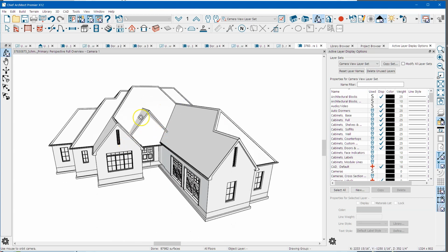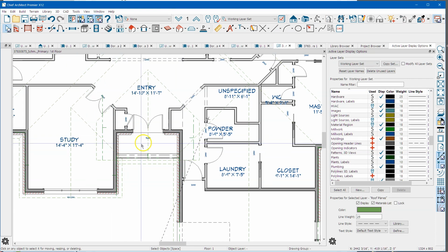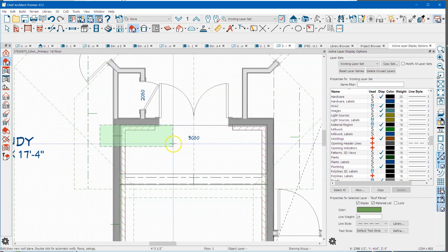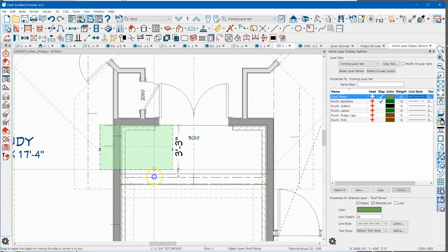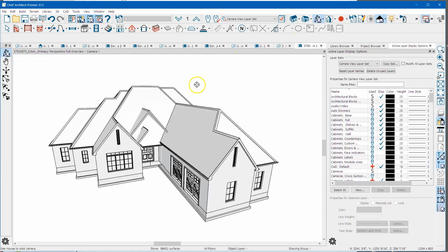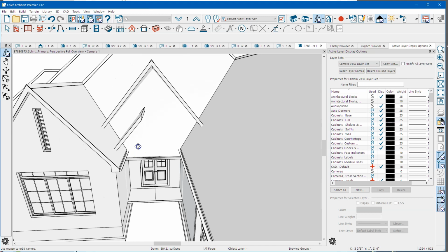It's easy to draw these. You know, drawing them manually is not a big deal. You've got walls here that you can draw off of. So I can come in here and I can pick either side. I'm just going to pick this side over here. And you can draw a roof plane right there. I'm going to just drag it out so we can see it. And so there's that roof plane. So drawing them is, once you've drawn one, they're trivial to draw.